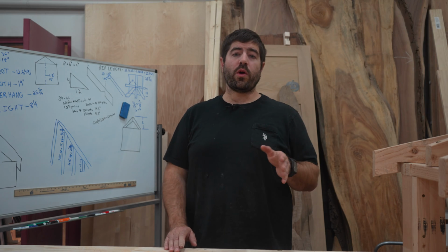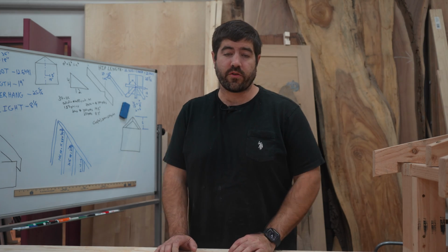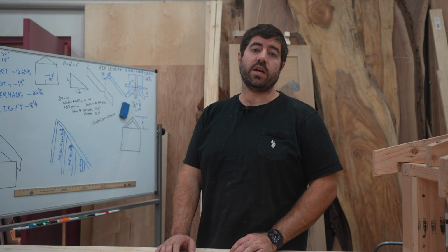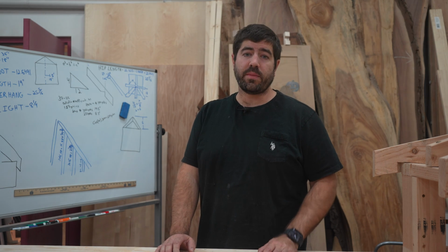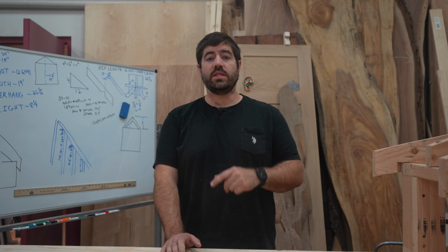As I said, I will be going over how to install the subfascia in the next video and how we normally straighten the tails of the rafter on the job site before installing the fascia. For us, it's normally done on factory-made trusses, which never have tails that line up. But as I said, I will cover this in the next video.